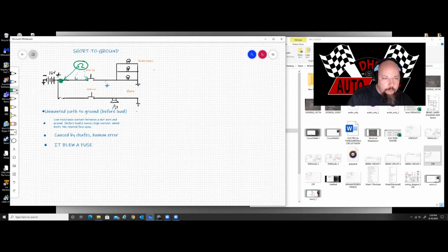And as you do that, okay, right here with the switch closed, if you probed here, you would notice nothing. If you probed here, you would notice nothing. It would still read open circuit, OL, on the meter, okay? So you have nothing here and nothing here at the switch, okay? Leaving this switch open, however, leave the switch open. You come on over here, and then all of a sudden, maybe you see an ohms reading, 0.1 ohms, 0.2 ohms, low resistance contact. Uh-oh, I have got a bit of a problem here. Okay, so I know that I'm on the right path. So I can go ahead and get rid of the idea that it's over here or over here. Right, so I'm still tracking this thing.